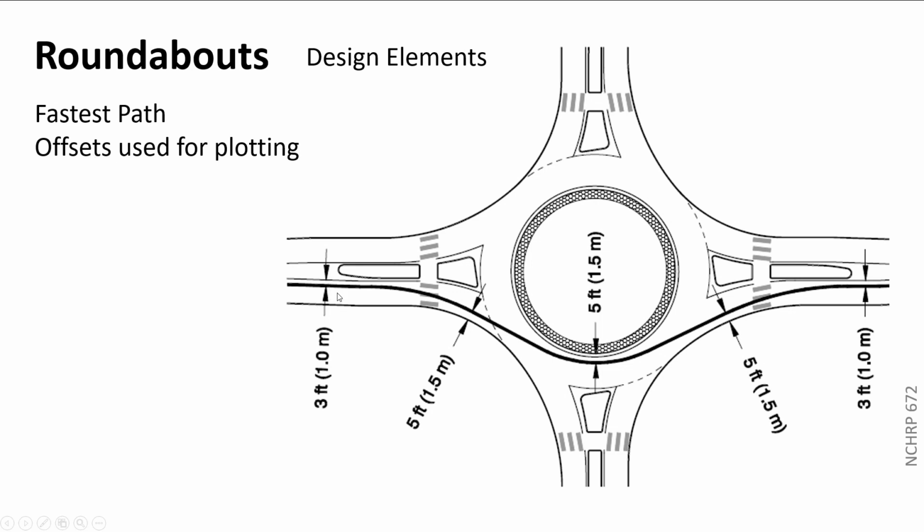This is how we would draw it, and like I say, we often used to use a spline curve to pass through these points, and you'd spend a fair bit of time trying to make them nice and smooth. And this is from the guide. They suggest that at the beginning, the center of the vehicle will be 3 feet off of the inside striped line of that lane. So that car is hugging that inside line, because they're like a race car driver. They're trying to get through this curve as fast as possible. So they hug this side.